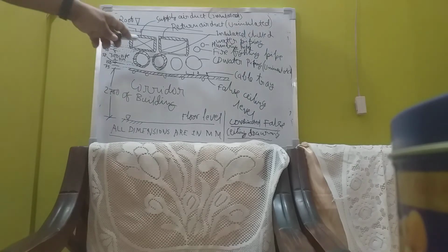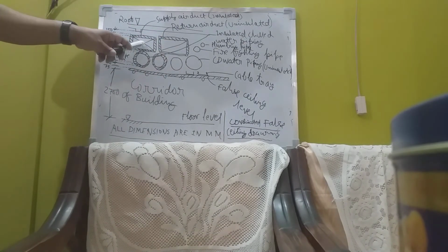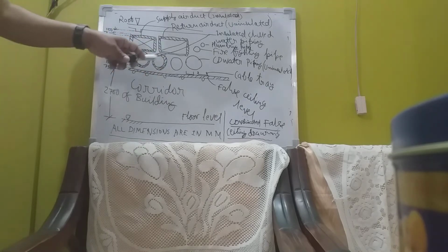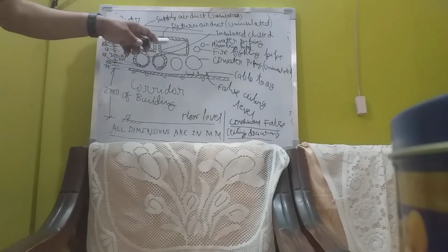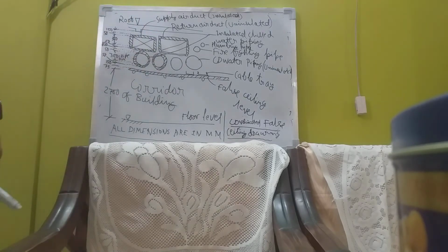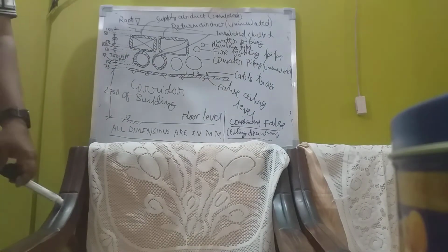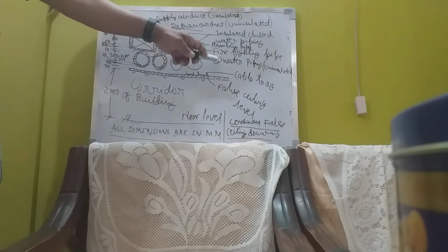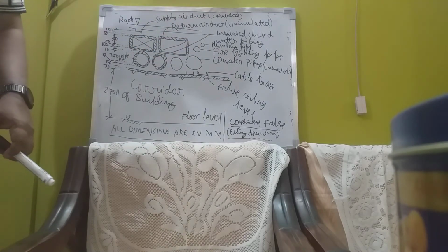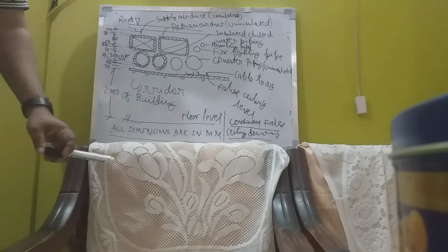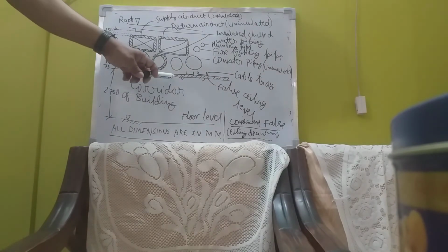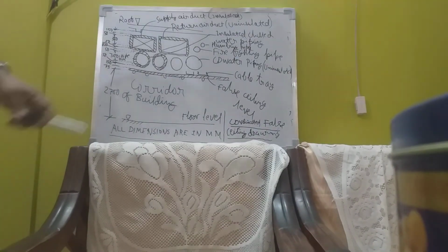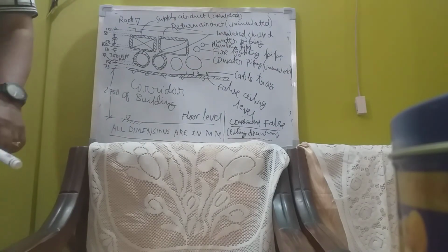अगर HVAC का सारा सिस्टम नहीं होता, तामझाम नहीं होता, ये chilled water pipe, condenser water pipe, supply air, false ceiling height would have been much higher. Architect would have been very happy because this is a small firefighting pipe, small drain pipe, small other pipes going, gas pipes are going. So these are small pipes. So he could have easily manipulated the higher false ceiling height, but he cannot do it because of HVAC.